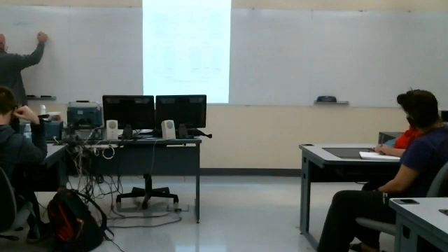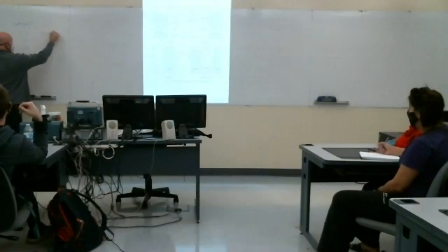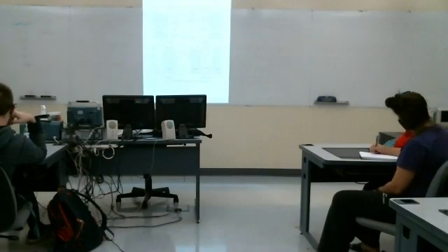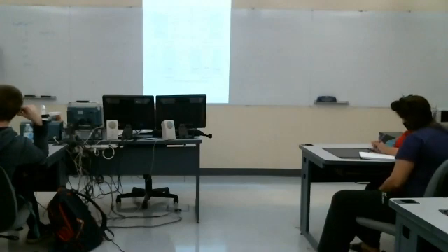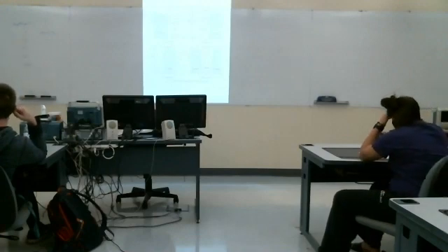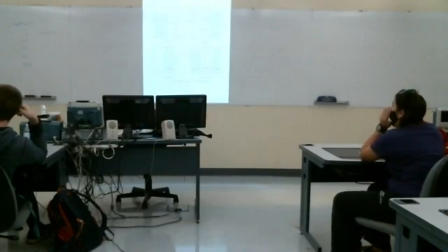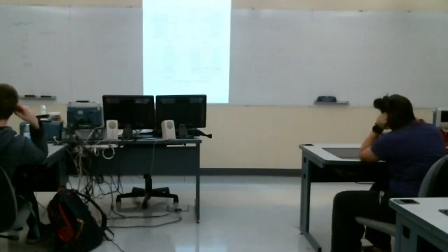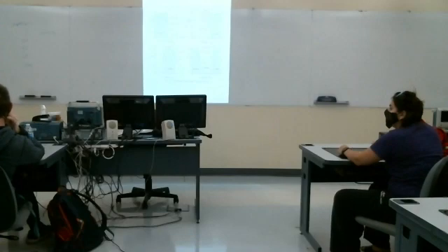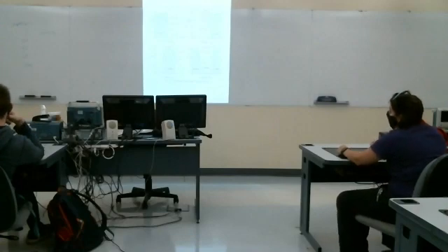Remember, this is the output over the input. So a linear gain of 1, where the output is equal in amplitude to the input, means a gain in dB of 0. So a 0 dB gain doesn't mean no gain. It actually means the output is the same amplitude as the input. Positive dB values mean that the output is greater than the input. A 20 dB gain means that the output is 10 times the amplitude of the input.